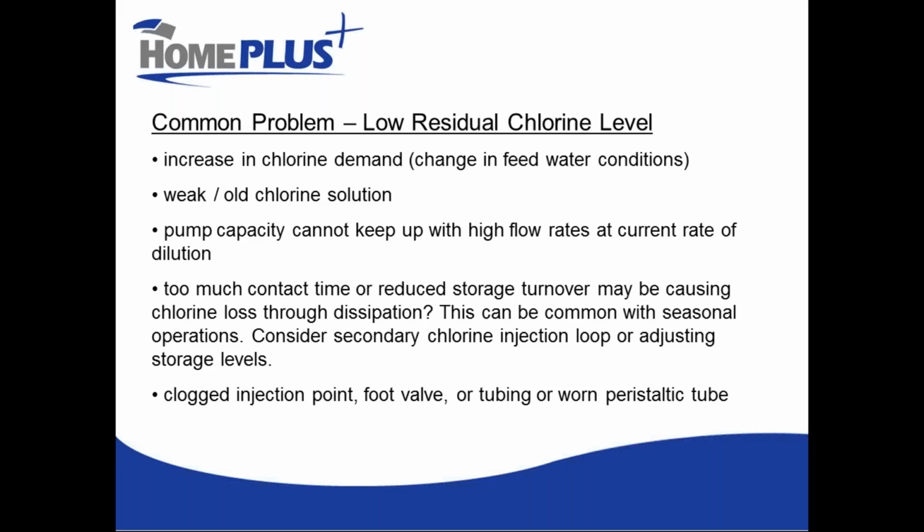Sometimes you'll have a situation where your pump capacity cannot keep up with higher flow rates that might be happening from time to time. If you've had increased demands on your system, particularly related to flow rate, you can watch for this problem by listening to and watching to see if your pump continues to pump once your water flow has stopped.